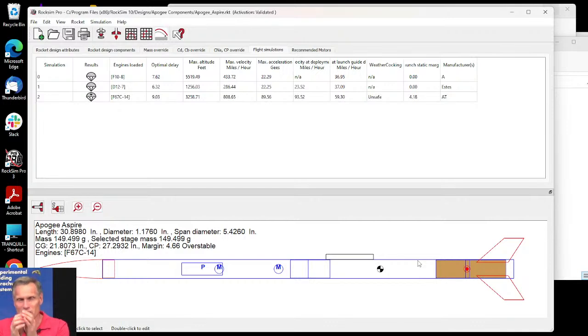If the flame is going through the tube, you might not get optimal expansion of the flame, because in a rocket motor, you're creating a venturi. If you cut a nozzle in half, you have the converging section of the nozzle where the propellant's over here and it gets smaller, and that squeezes the gases, and so they go really fast until they get to the nozzle throat, which is the smallest point in the rocket nozzle, and that's called the choke point.